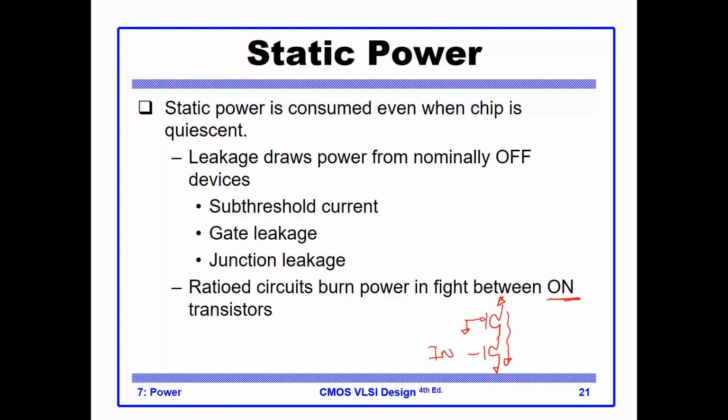These kinds of circuits are really discouraged nowadays, and they are used in very limited types of circuits, because they draw this static energy even when they are switching the inputs. People are discouraged from using these circuits except for very limited cases like wide NOR gates for the ROM implementations, etc.